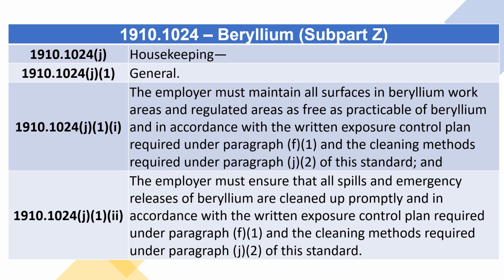1910.1024 J1(i) The employer must maintain all surfaces in beryllium work areas and regulated areas as free as practicable of beryllium and in accordance with the written exposure control plan required under paragraph F1 and the cleaning methods required under paragraph J2 of this standard. And